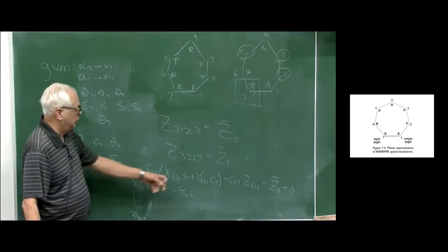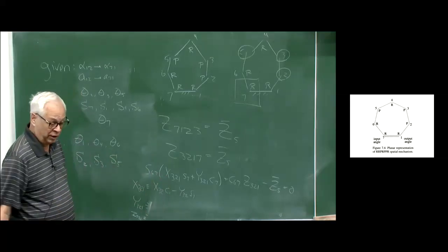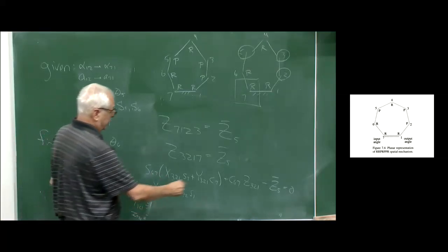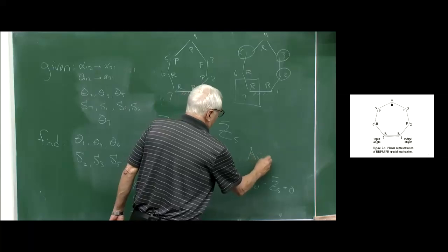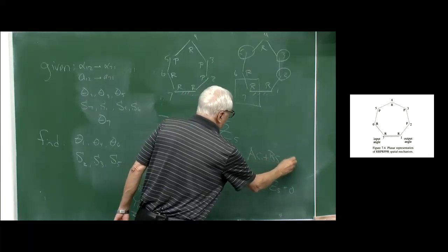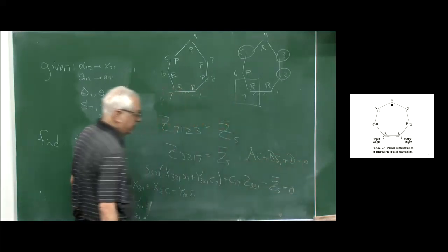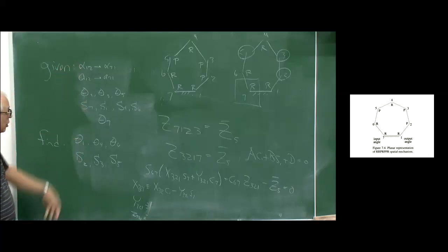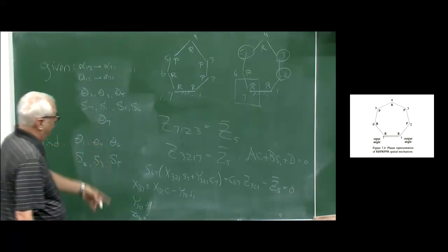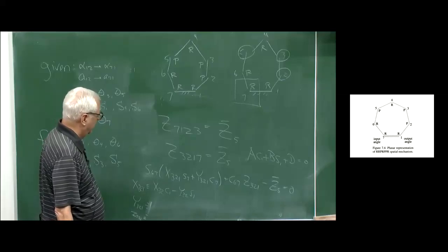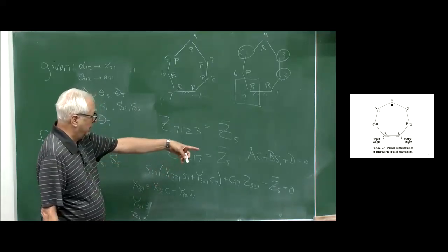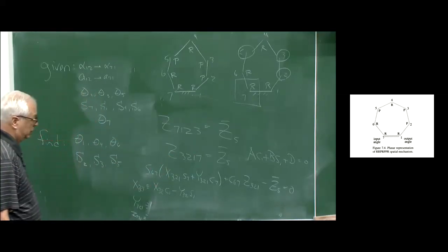And we have to substitute those in there, and we have to group all the unknowns together so that we will get it into this format of A cosine 1 plus B sine 1 plus D equals 0, where A, B, D will evaluate based on all the junk we're given, all the alphas. Given those 4 thetas, yeah, the capital A, B, and D will evaluate to numbers.